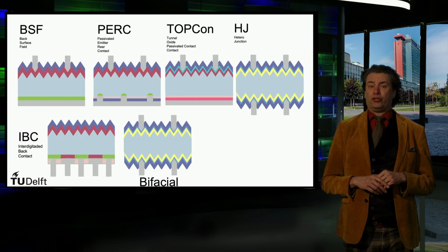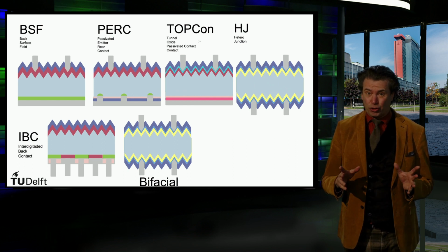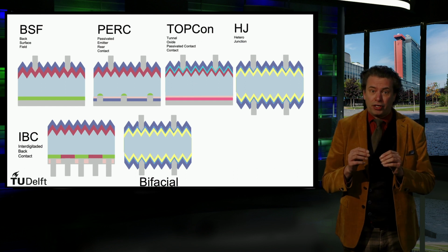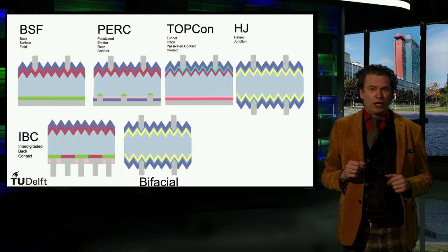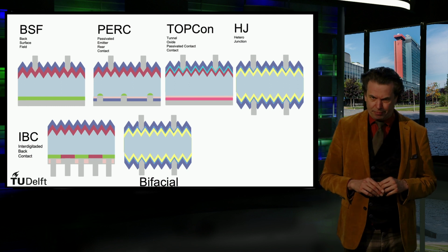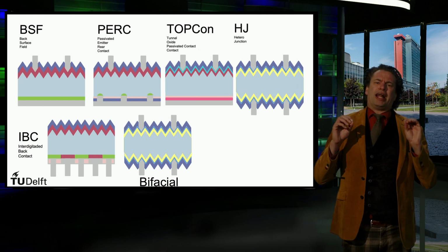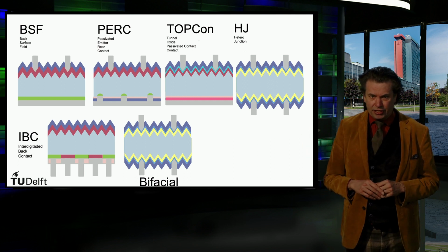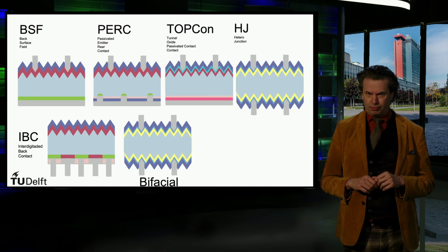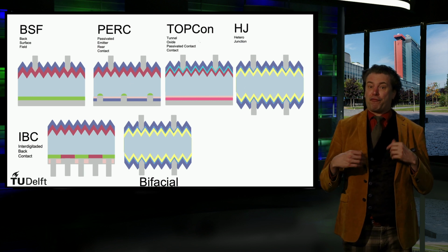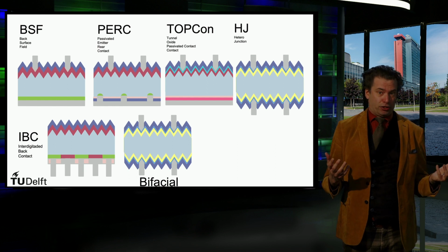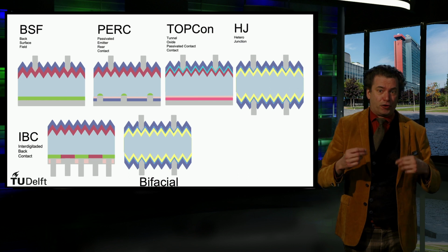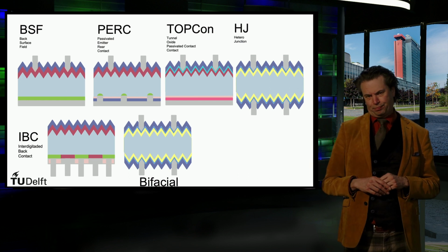As I already discussed with the crystalline silicon heterojunction solar cell technology, you can make an architecture in which both at the front and at the back side you place a metal contact grid. This allows light incident from both the front and the back to be absorbed in the PV active layers, increasing the cell's performance. This architecture is referred to as bifacial. Normal solar cells, including a non-transparent backsheet, are referred to as monofacial.